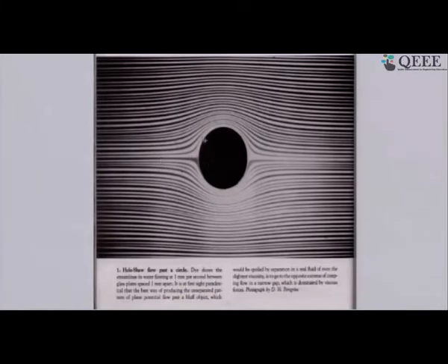Now let's see what happens in this portion. The streamline came here and then almost turned very sharply and went off. This is not a 90-degree turn, but if it were all the way here, then locally it would go 90 degrees. But this is a fairly sharp bend, then it comes up, recovers, and again it bends and comes back straight. So there is something happening here: the flow is going up, and at some points here you can say that the flow is actually parallel to the surface of the cylinder. That gives us a thing: if I know something about the flat plate boundary layer, with a little bit of approximation I can try to understand what happens over here. And then it goes up over here, the velocity has increased at this point, and then again it comes back and decreases. So this is a very low Reynolds number flow.